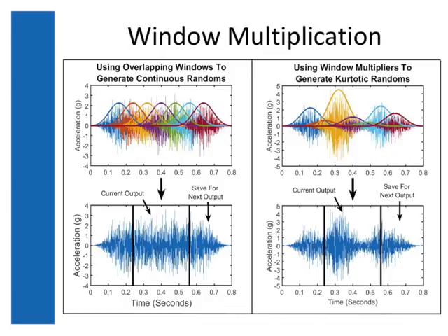So to make kurtosis, we just multiply each buffer by a random positive number. And actually anyone can do this. Two rules. First, whatever distribution of multipliers you use has to have an RMS value of 1 so that you don't change the total test level. Second, you have to have at least one tunable parameter so that you have some empirical handle to control kurtosis. This method has been in the public domain for years, so anyone who wants to make just a quick and dirty kurtosis controller can use it.